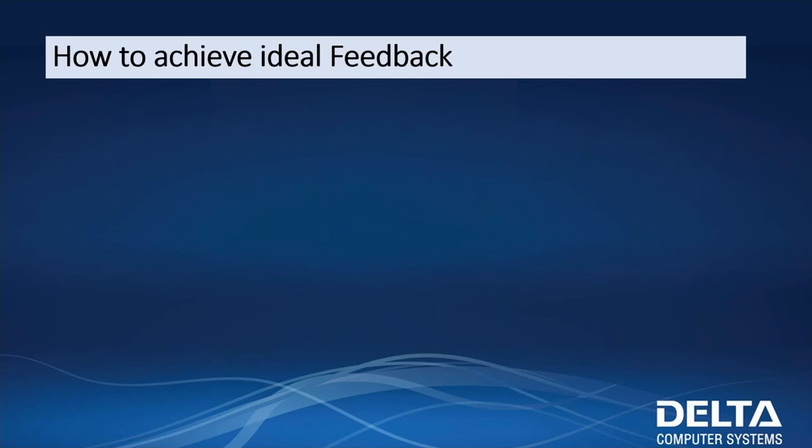So how do we achieve ideal feedback? Well, funny enough, a lot of times it comes down to grounding, especially with analog feedback. It's kind of funny, but you would be surprised at the amount of times we see the analog minus pin is connected, but the ground pin on our RMC is just left floating. And so sometimes that analog feedback is correct. Sometimes it just loses control.